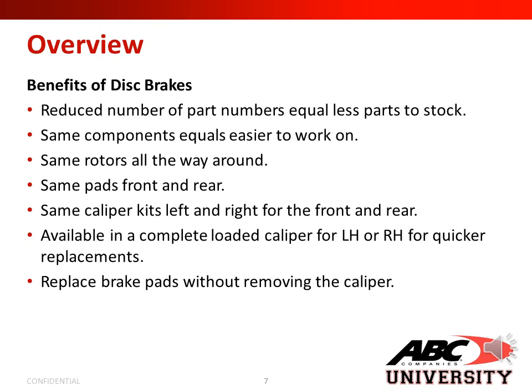Now let's go over the benefits of disc brakes. You have a reduced number of part numbers equals less parts to stock. Same components equal easier to work on. Same rotors all the way around. Same pads from front and rear. Same caliper kits left and right for the front and rear. Available in a complete loaded caliper for left hand or right hand for quicker replacements. And you can replace brake pads without removing the caliper.